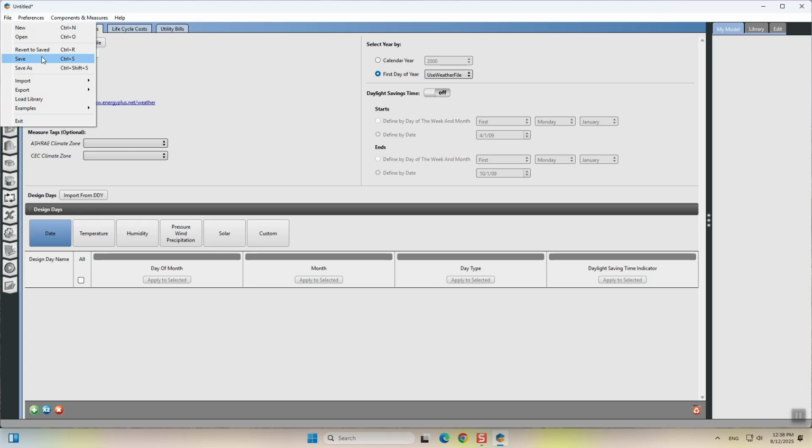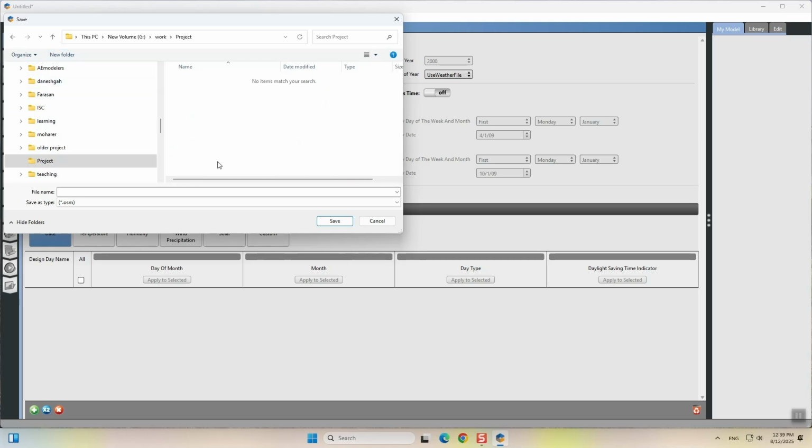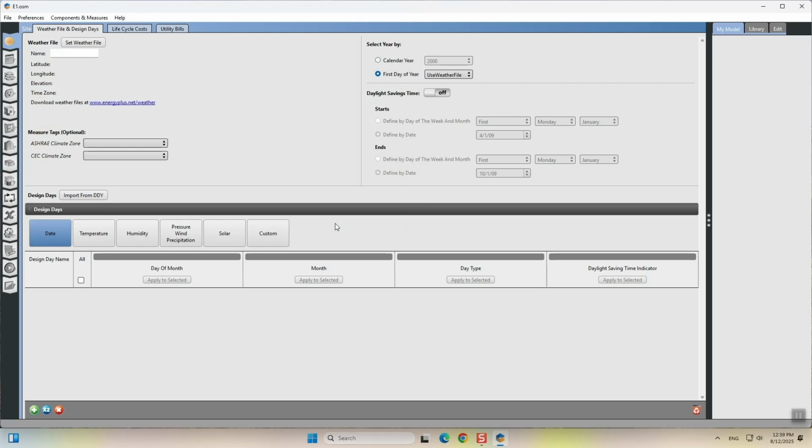This way, if you hit a snag, you can roll back to your last save instead of starting from scratch. Kick things off right by heading to the File menu and choosing Save. A dialog will pop up, letting you pick a working directory and name your model. Saving creates an OSM, OpenStudio model file. Think of this as the main file you'd share with others along with a matching directory. That directory will eventually hold supporting files, simulation results, and more. Let's get saving and start building.